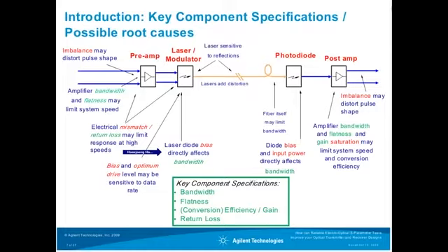For instance, a photodetector that is not properly biased has neither a large bandwidth, and it also shows saturation effects at high optical input powers, which decreases the effective and useful bandwidth. So all these different components and effects you really want to measure, and one way of doing these basic measurements is through the optoelectronic S-parameters.